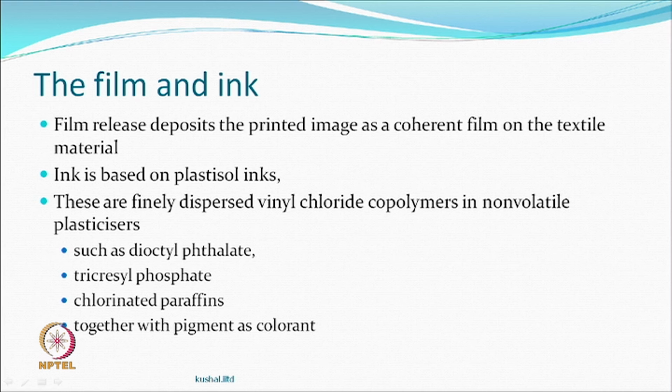Plasticizer is a compound which reduces the glass transition temperature of polymer and film in this case. So, it remains flexible, right. If you have a large number of polymers which are flexible polymers, you have plasticizer in them. Sometimes the plasticizer with time can ooze out, and you may have seen with time the polymers, the sheets, they become rigid with time, because the plasticizer can ooze out and come.